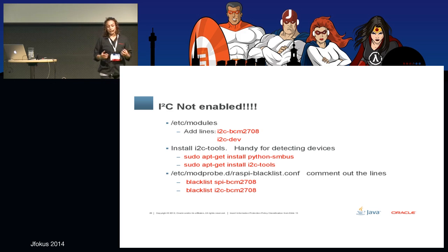Why? Because if you jump into the code right away and things don't work, you don't even know if the Raspberry Pi is able to see your device. So before you even move to the code, make sure the hardware is working properly. Make sure the OS can see that device. And this is what these I2C tools were very useful for. So again, it's not required, but I do encourage you to use them.